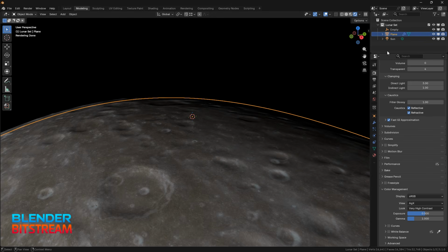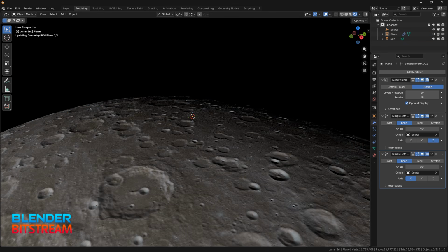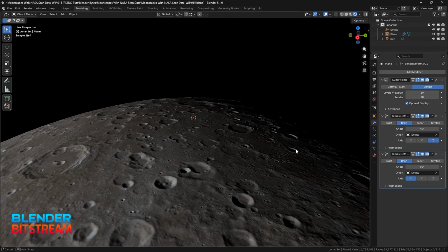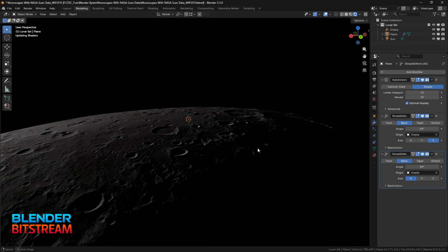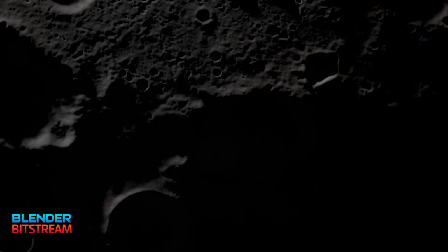Now that everything is ready to be rendered, I'll turn the subdivision modifier up to 10 so the full range of the height data can be seen. If you're worried that your rig might not like this, increase it one iteration at a time. Scaling the images down also helps on lower end specs. Hopefully this gives you a clean, reliable workflow for your lunar landscapes.